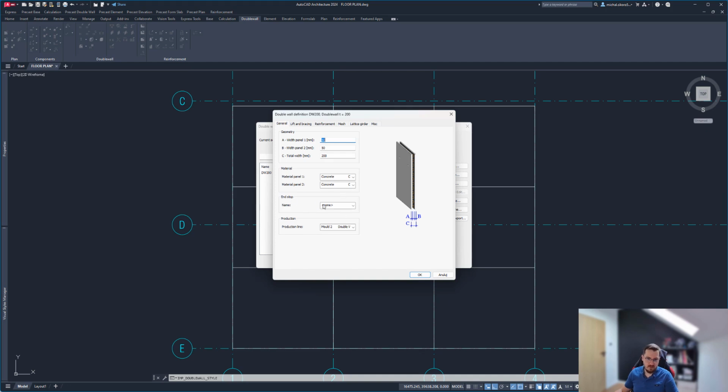We can also create end stops, and we will also be able to add end stops at other points during the whole modeling phase, which I will be mentioning if I remember about mentioning that. But yeah, so if you don't want to remember about adding special formwork or something to keep the concrete inside, then you can just model end stops with your double walls as well.